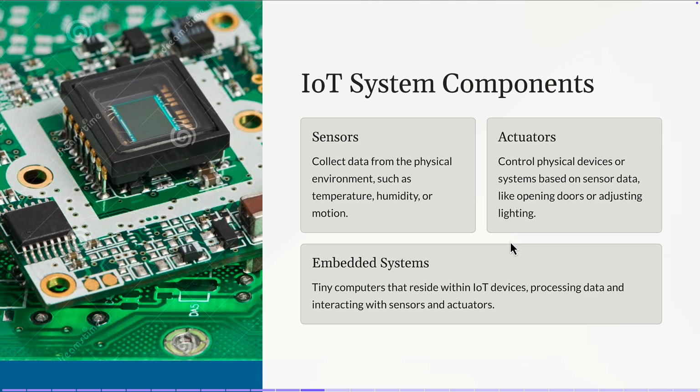Or I can use it depending on the event. For example, if I have a plant and I want to measure the energy of the sunlight, I could turn it off at night and turn it on in the day. Yes. If you make, for example, a moisture sensor, maybe you need to monitor this once a day to save energy. So it depends on the use case. You will define what we call the duty cycle for the system.